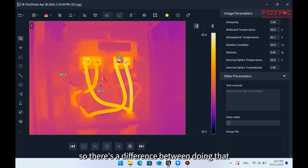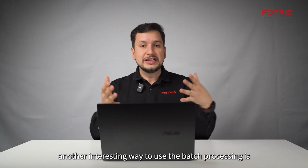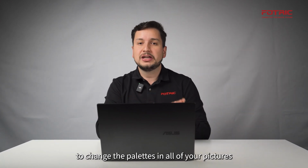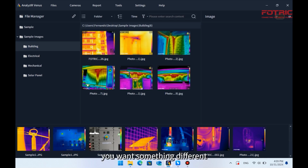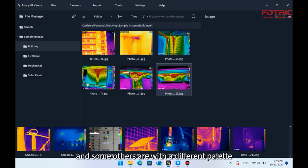So there's a difference between doing that, as you know, and doing the general process, which I'm going to show you right now, where you would have to go picture by picture, opening the picture, creating the spot, and then drawing the box. Another interesting way to use the batch processing is to change the palettes in all of your pictures. Let's say that for electrical you're using iron palette, but for building inspection you want something different. So you see that some of these are with iron and some others are with a different palette.